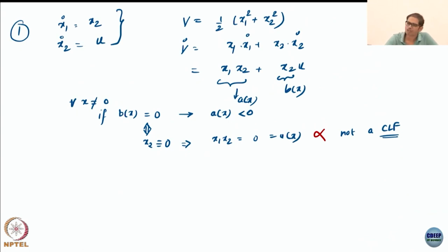That seemed to work. Do you remember what kind of Lyapunov function I used to prove that the system was stable in that case? It was complicated, not very straightforward. If you remember, x1 square plus x2 square did not work because it's not a strict Lyapunov function.